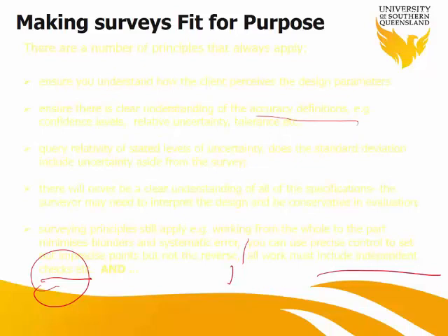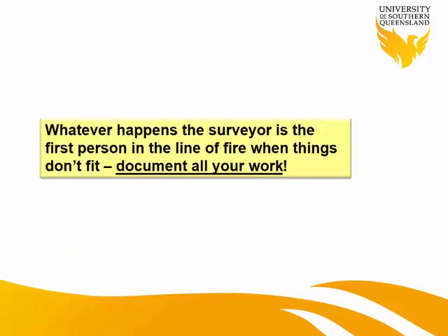But is it the most important? No. To me, the more important one is whatever happens, they're going to blame you as the first person. So make sure that you document all of your work and keep a record of every field note and every drawing, plan and sketch that you have, because someday you're going to need them to prove that your work was traceable and you did everything you need to do, and you looked at all the specification and accuracy, you did all the analysis and error assessment. So these are the documents you need to have, keep record of them.